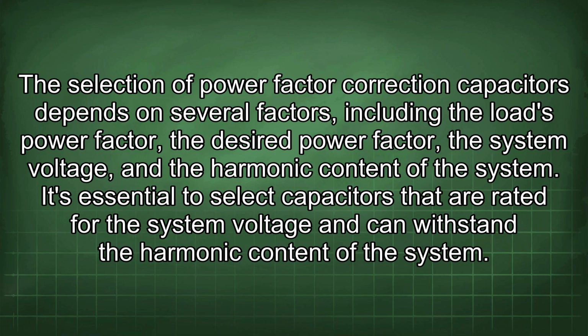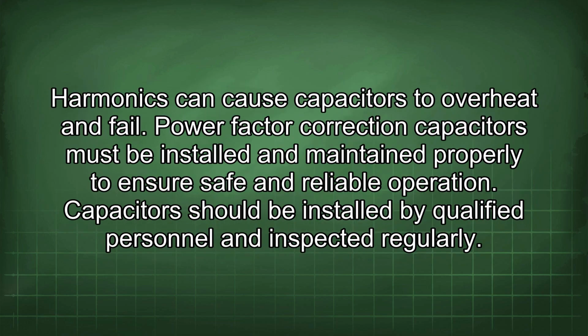The selection of power factor correction capacitors depends on several factors, including the load's power factor, the desired power factor, the system voltage, and the harmonic content of the system. It's essential to select capacitors that are rated for the system voltage and can withstand the harmonic content of the system. Harmonics can cause capacitors to overheat and fail.